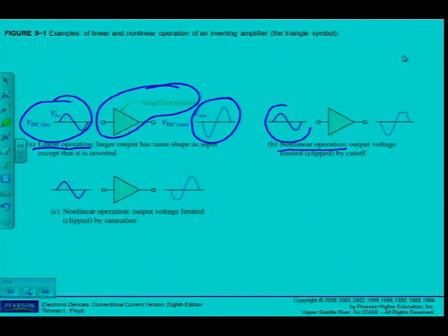There is my small input signal, and on my output signal I can see there is distortion. We'll discuss the reason for it now, but you can see in this case my Q point was too close to cut off. The reason why it shows on top is because the signals are inverted. I know that my cutoff point is at the bottom of my load line.